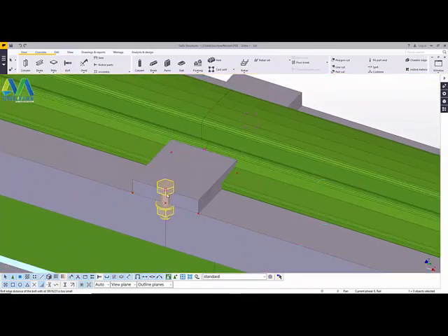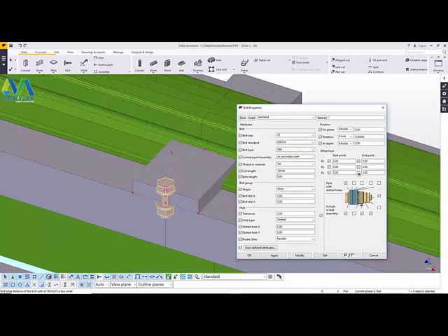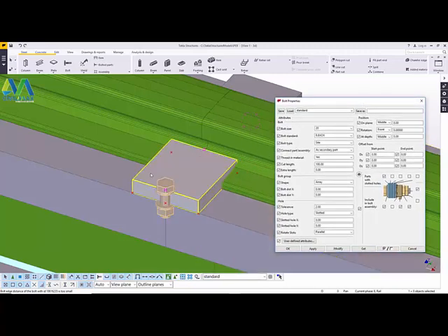By default, just double click on it, and we need a washer there, and change the size. We can use M16, or we can just leave it at M20, which is okay. Just click apply, and we have a washer. We didn't have a washer before, because I've just checked these washers. Now we need 2 bolts, this side 2, and that side 2.